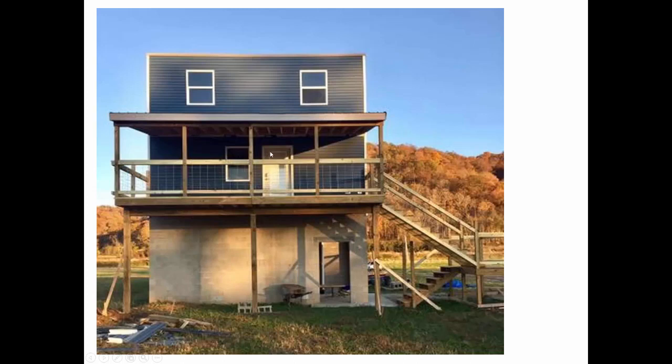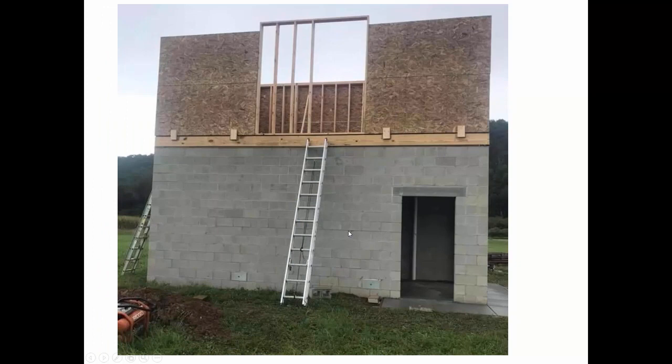If this is the width of a door, then the house is only maybe like 6 times wider than a doorway. And by having relatively flood-proof building materials like cinder block walls down beneath and then not having any of the OSB or wood until you're at the elevation where you wouldn't expect to see water very often, it's a smart way to use land for residential use that otherwise is too risky to build on: just elevate the structure. And that's Route 2 to the right of that structure. Mm-hmm. That little white gravel area, that's Route 2 back there.